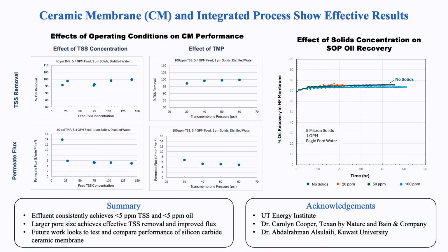Here on the left side, you see the results from our 1 micron average size particle testing. We can see that the ceramic membrane was able to obtain very consistent and very effective TSS removals across all conditions, achieving over 95% removal for all of our tests.